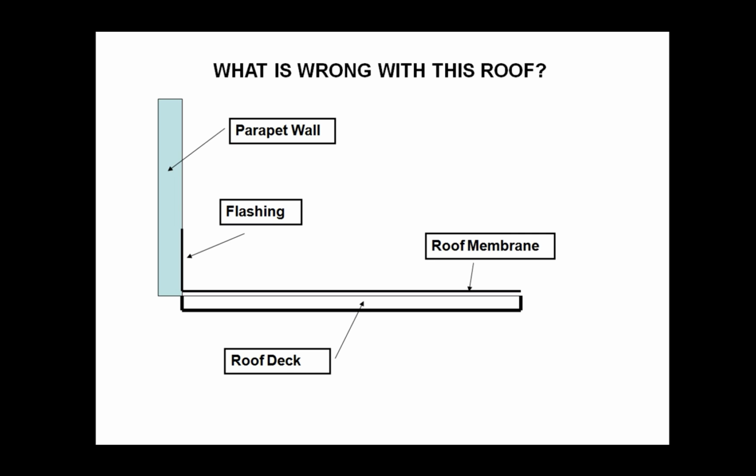Okay, and so from what we know, your issue is where the flashing is. Now typically you want flashing to either come up and over the parapet wall, but in this case you have a high parapet wall, so what you would like to have is that angled entry. As we saw earlier in class, down in that right angle where the roofing membrane curves up into the flashing, generally you'd have a triangular block underneath there, forcing that up on an angle, and then the flashing entering the parapet wall at some point and then sealed.